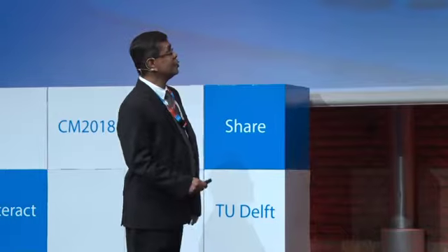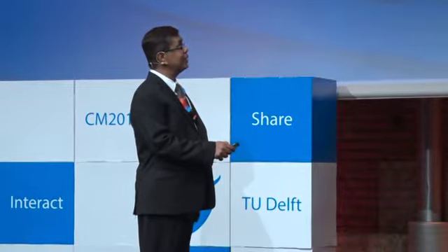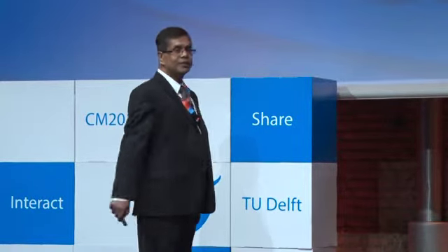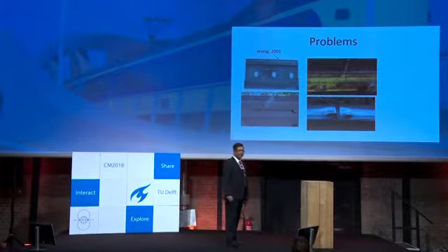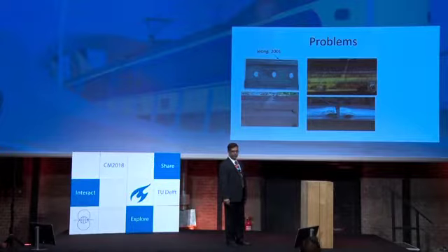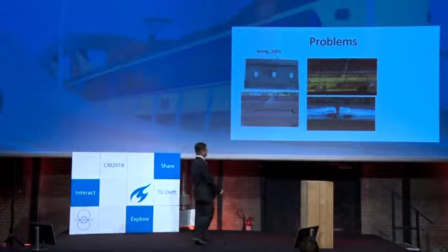Now, why is this bar important? This is the end of the rail, and the bending rigidity of the joint at the gap is finished. There is no joint, no rigidity. So to cover that rigidity, to back it up, the joint bars are used. How much can they cover? Two thirds of the bending rigidity of the continuous rail is covered by the joint bar. That is why this connection piece is considered to be one of the weakest links in the track.